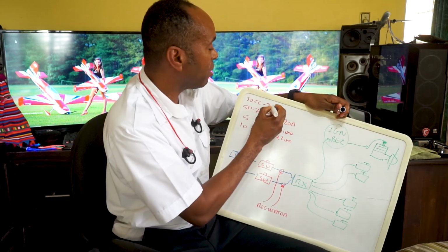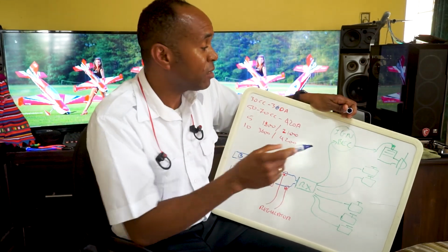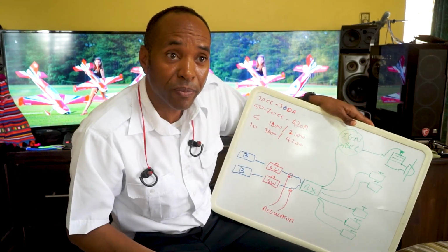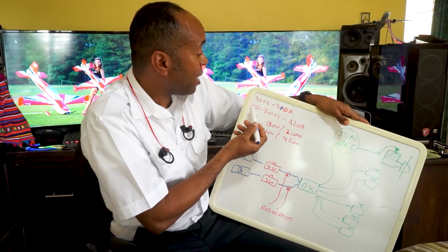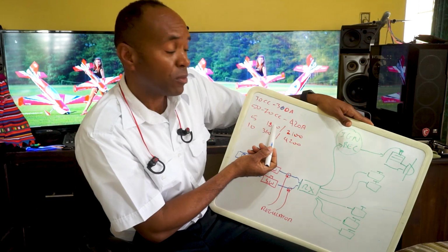Let us say 300 milliamps per flight, average, right? What you need to do is decide how many flights you're going to do for the day. Normally I do 5 flights per session. So 5 flights with a 30cc airplane will give me 1800 milliamps.